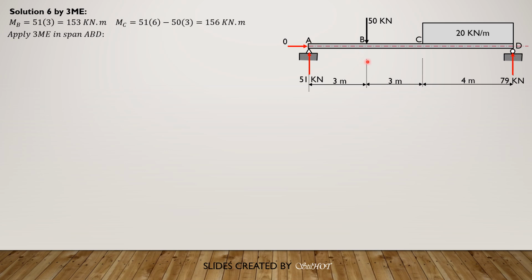we have the same vertical distance from the horizontal line through the elastic curve at B. HA and HD will be the same, and they are equal to the deflection at B. So that's the elastic curve. This is the horizontal line through point B on the elastic curve. This is now the position of B. Then this is HA supposedly. Then this is the deflection at B. And we have H sub D. So HD and HA are equal to delta B.